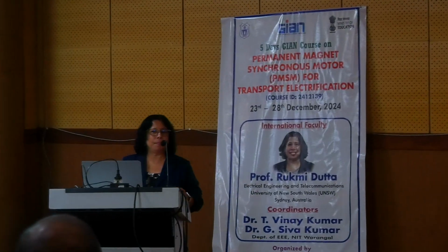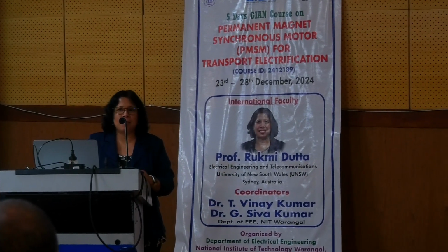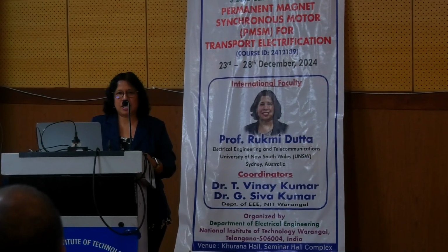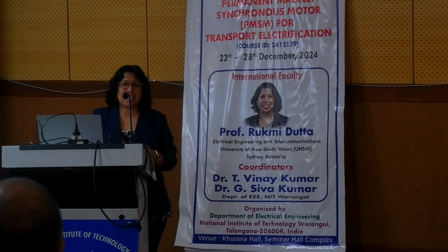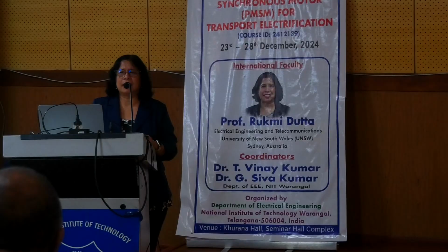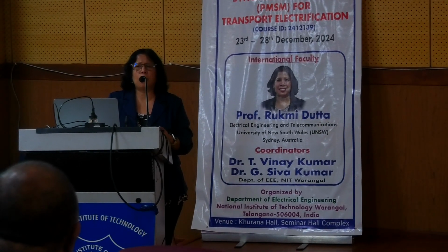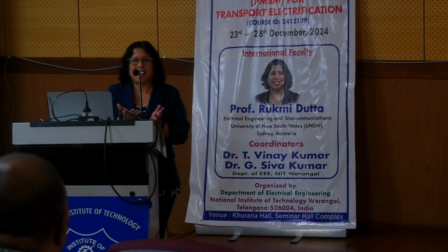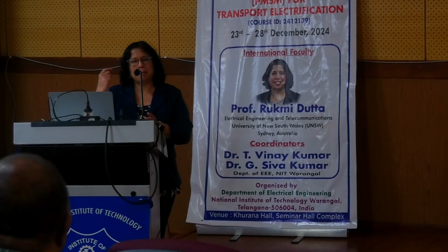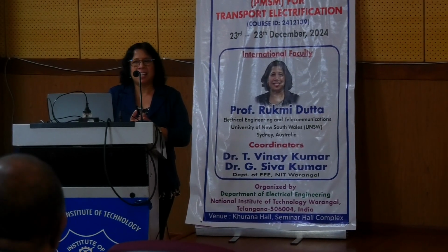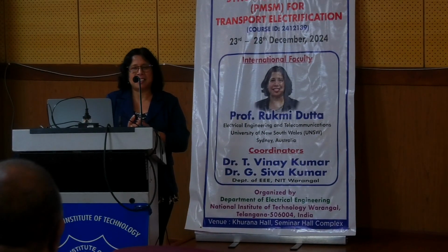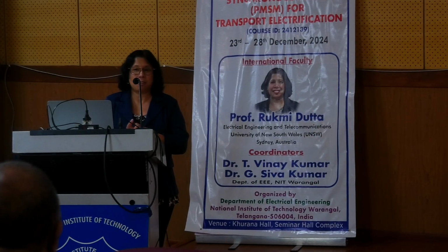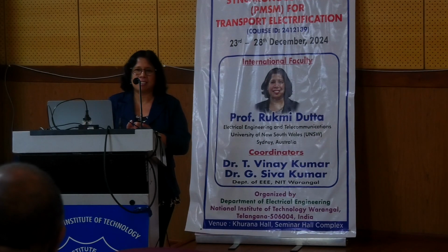What's the power density of the 7 centimeter motor that you have? I think the kilowatt per kg, I remember, is about 6. Kilowatt per liter, I can't remember the exact value, but it is pretty high, as you can see from the size. It is a very, very power dense motor. Power dense, not torque dense, because it's a low torque machine.